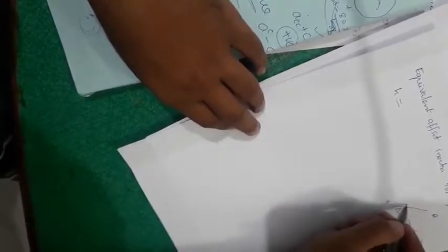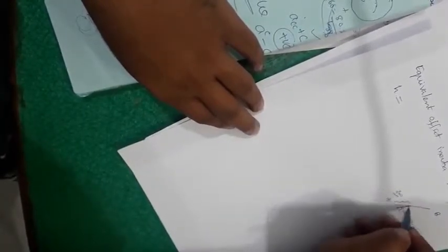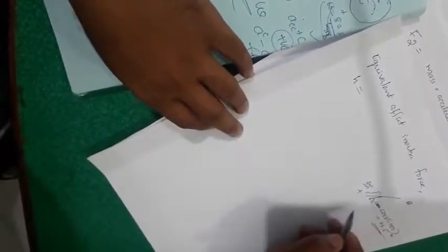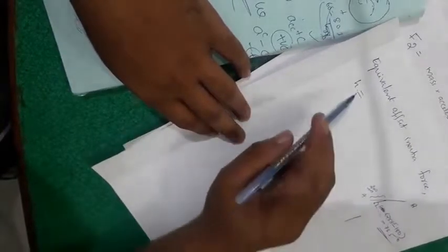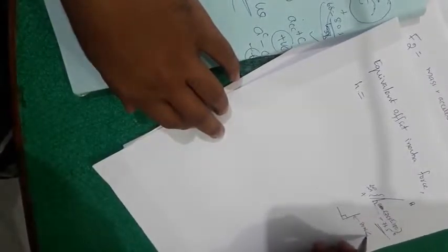Okay, so this was the original center of mass which was given in the question, that is 200 mm from the fixed point A. So we have to consider the inertia couple acting on this link. Taking this force, we have to draw a perpendicular from this force. So this is the force, that is 80 Newton angle 73.5 to the surface.